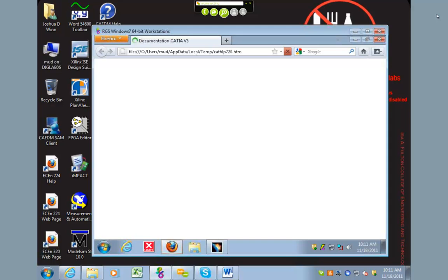And so you can only rotate in one direction, like around the Z, Y, or X-axis, and it can't translate or anything else like that. So we'll be using the revolute joint today. We're also going to be using a cylindrical joint. This one allows rotation in one direction, but also allows translation in another direction. Okay? And then if you're curious about any of these other types of joints, there's a ball joint, which is a spherical. There's a planar, which allows translation in 2 directions and rotation in 1 direction.